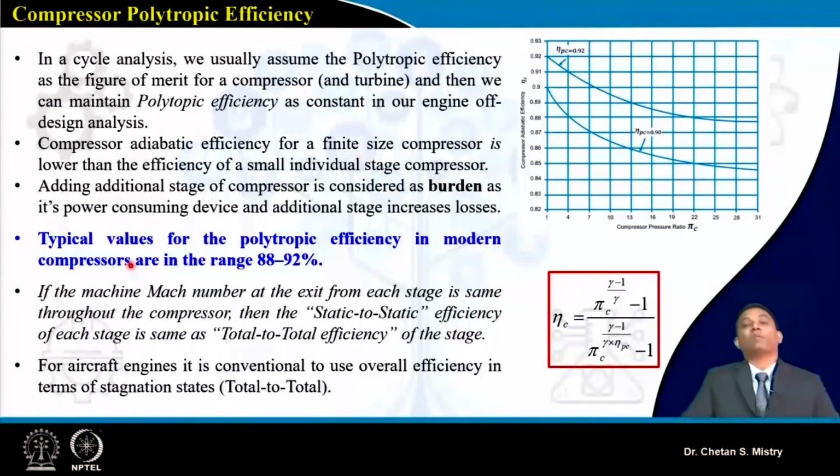And when we talk about commercial aircraft, where efficiency and fuel economy are major concerns, you are restricted in increasing the number of stages. Even for military applications, the length of the engine will increase. We cannot accommodate that engine within the fuselage that is provided for military application.